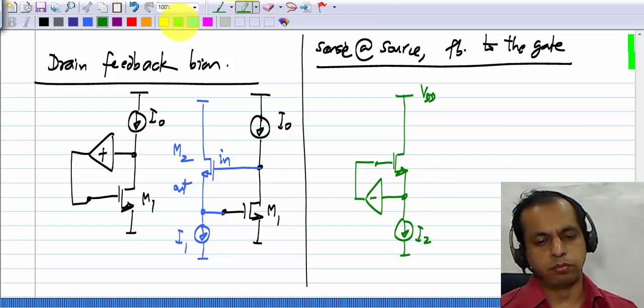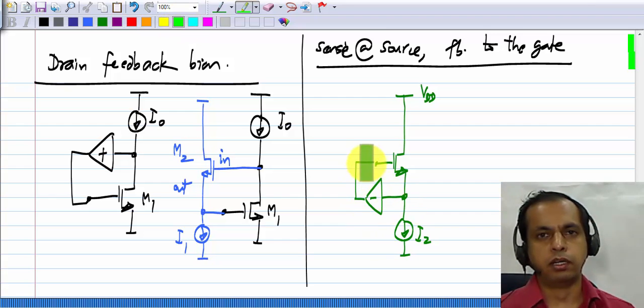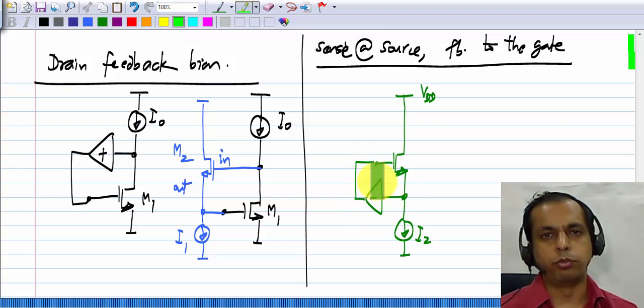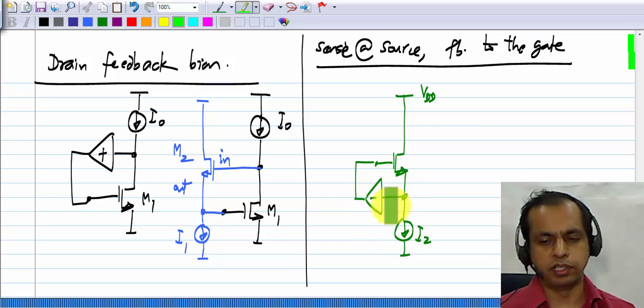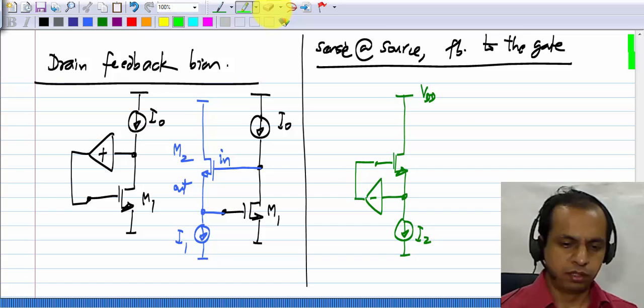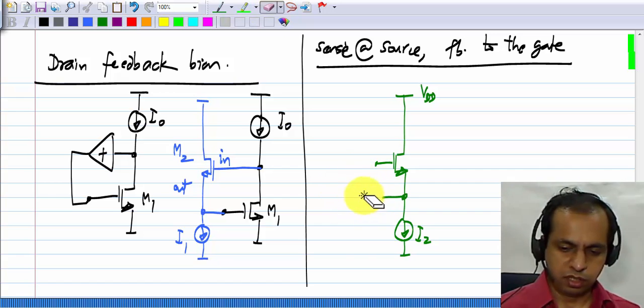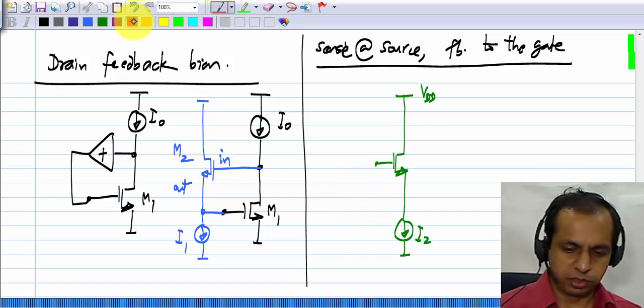Again, let's try some possibilities for this negative incremental gain. What possibilities do we have? One obvious thing is the common source amplifier. The very first amplifier that we discussed, it has a negative incremental gain. So let me use a common source amplifier in this place.